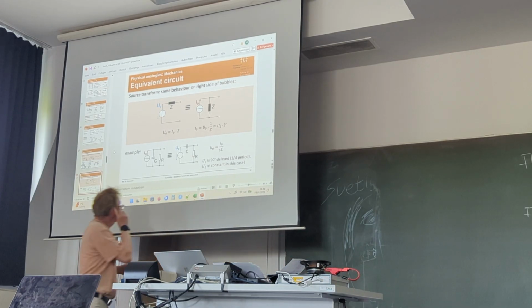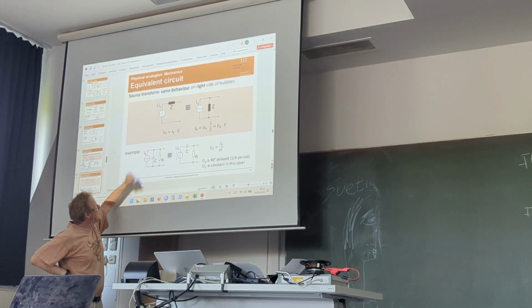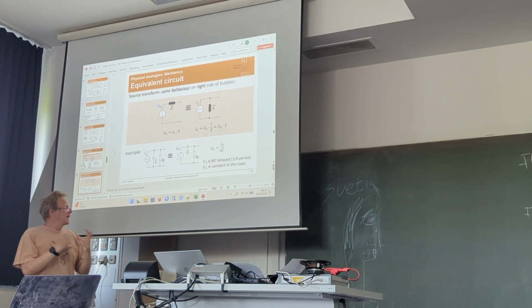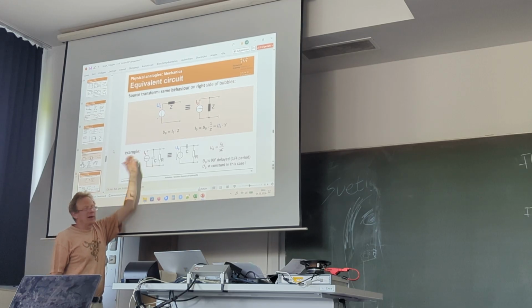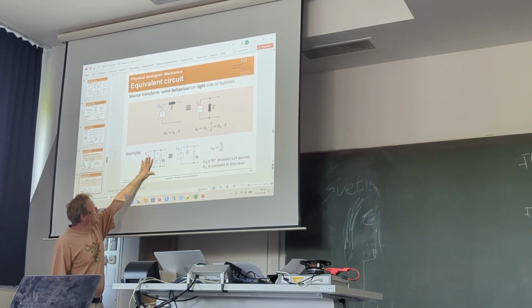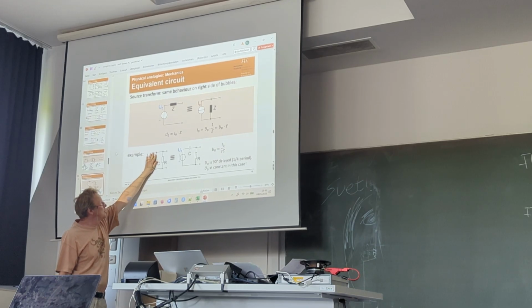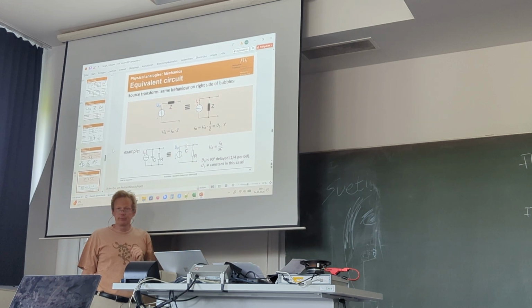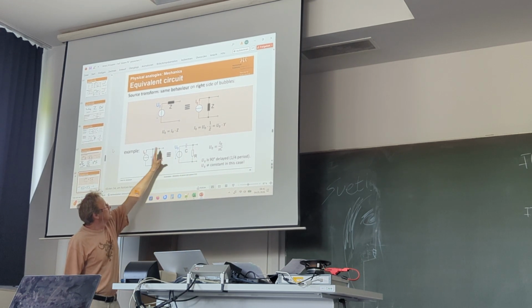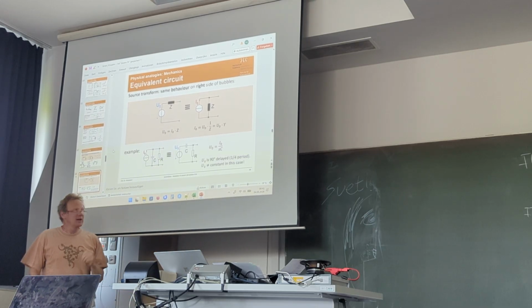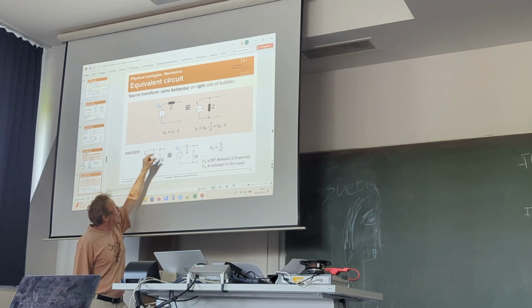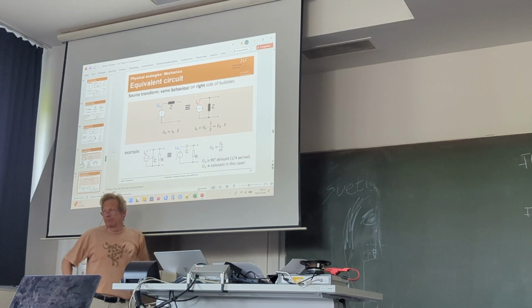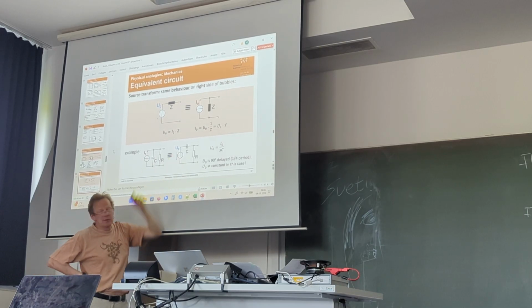So, for example, let's say we have a current source and parallel C and the R. It is possible just to take this current source and one parallel component, doesn't matter which one, for example the capacitor. Let's take these two, and you can form then a voltage source with the serial C. The R is then what will be connected here at the white bubbles, and then including the R and the bubbles here, there's no difference between these two circuits, as long as you calculate here the U0 correctly.